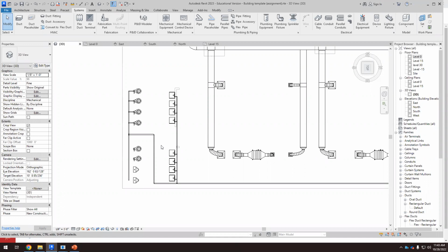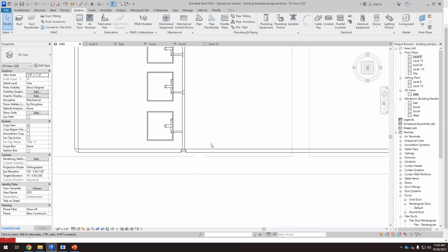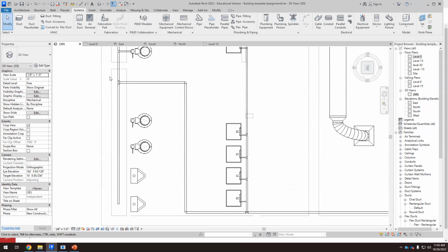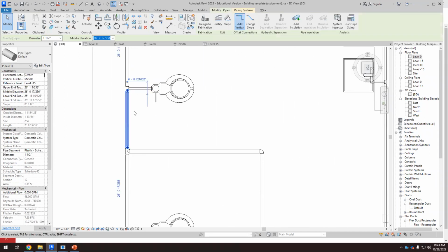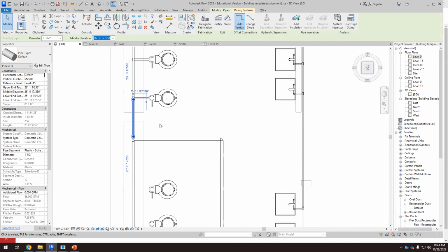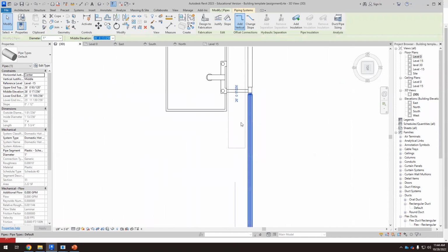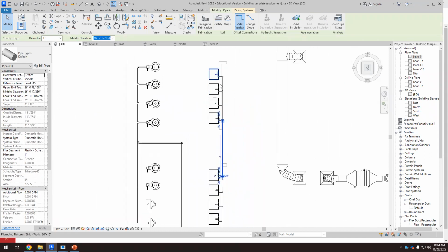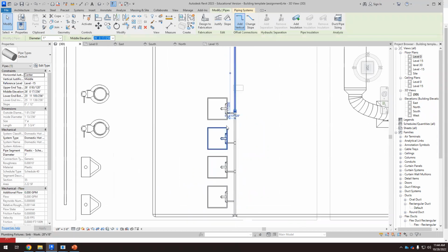But yeah, there are different options. So I don't mean that this is the best one, but the rule is, it's something wrong if we have here 1 inch and suddenly we have 3/4, that would be wrong. So if we have a half, when we have 3 or 4 half inch, then this branch has to be bigger. If we keep adding things, this branch has to be thicker.